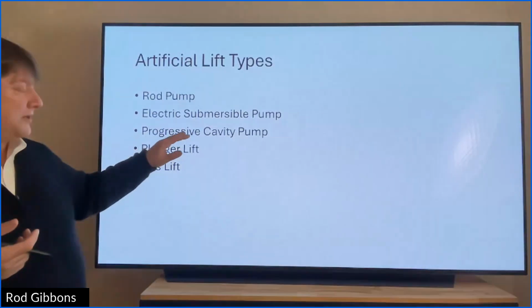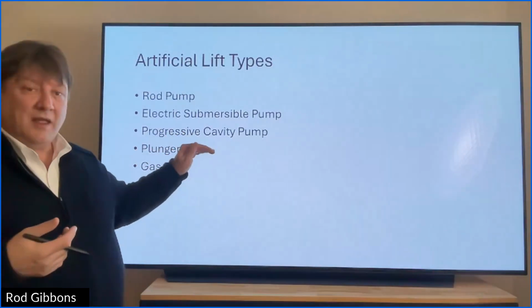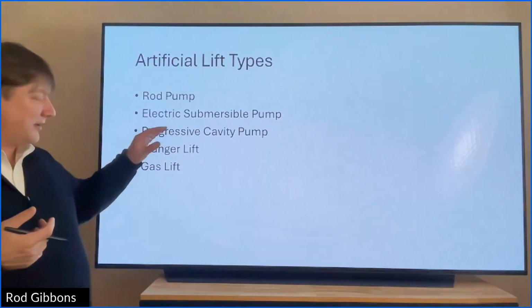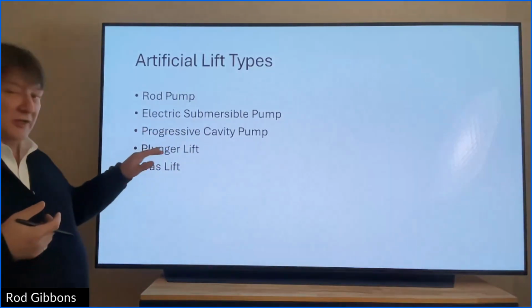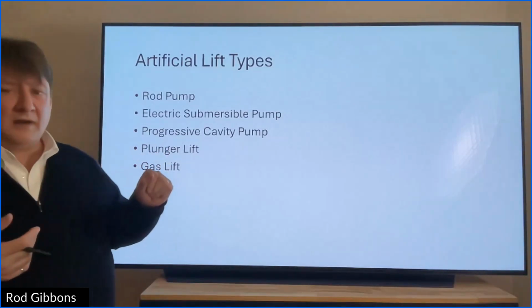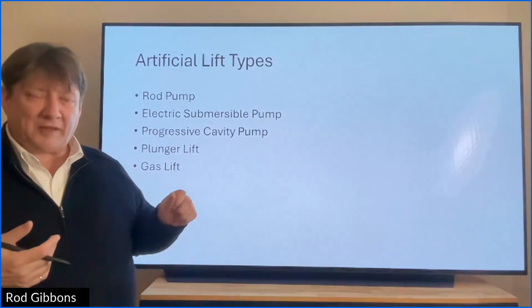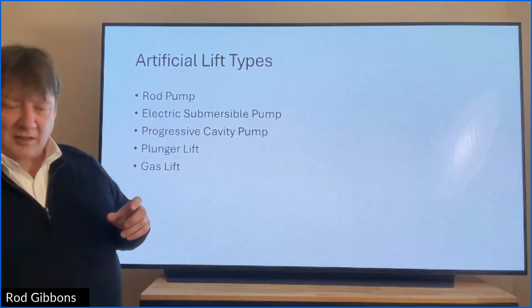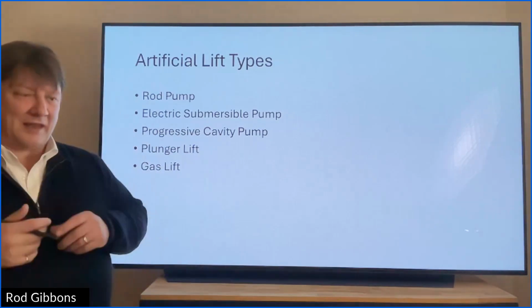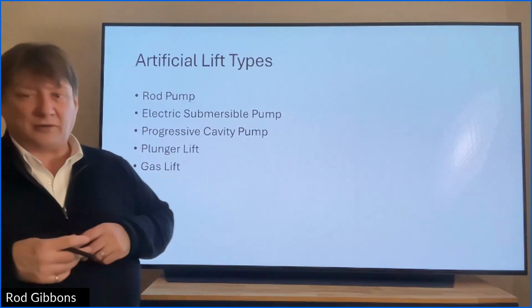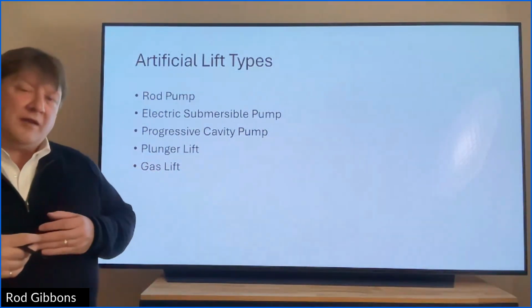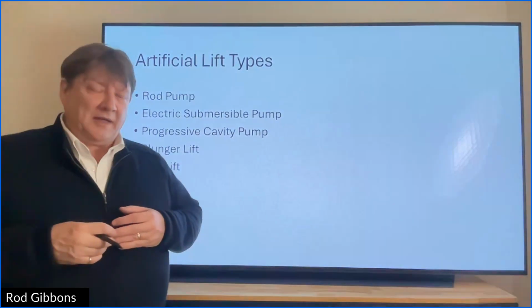Progressive cavity pumps, probably less so. They are good for pumping solids. So they've got a very specific use case. Plunger lift also, I would say, pretty popular in some onshore applications, because you're actually moving a metal plunger up the well, and so that works good. Onshore, offshore is not so good. Offshore gas lift is very, very popular option.